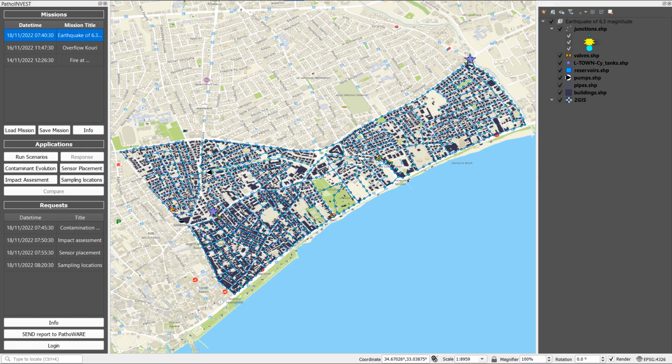In the contamination scenario, a certain contamination volume and time is preset as default. The tool can model the pathogen indicator Escherichia coli and 5 reference pathogens. 1 bacterium, that is Campylobacter, 2 viruses, enterovirus and norovirus, and a parasitic protozoan that is Cryptosporidium, that differ in their infectivity, persistence and resistance to residual disinfection.